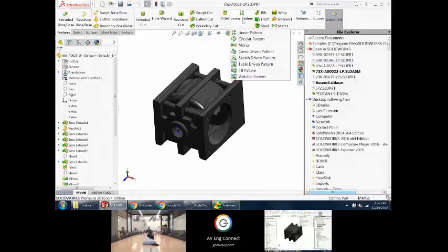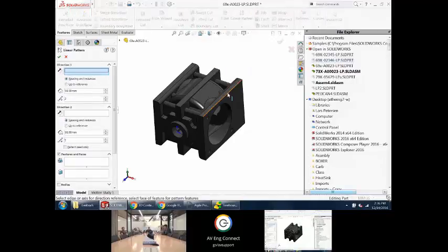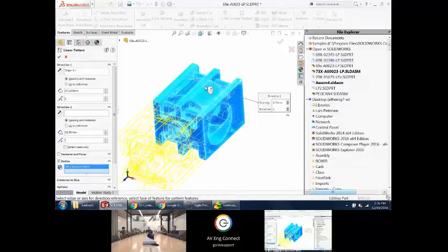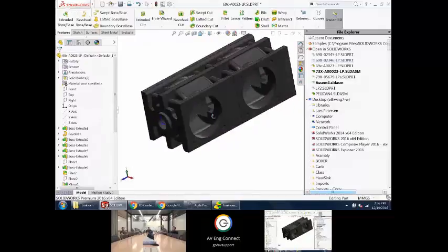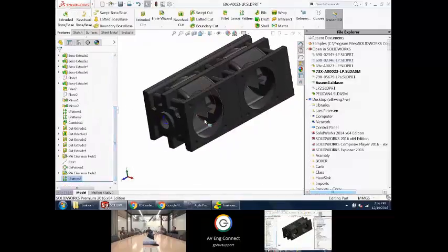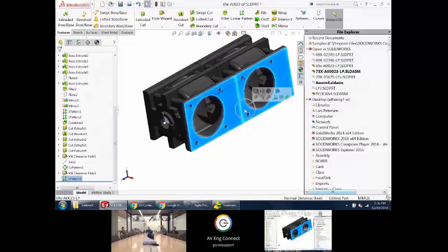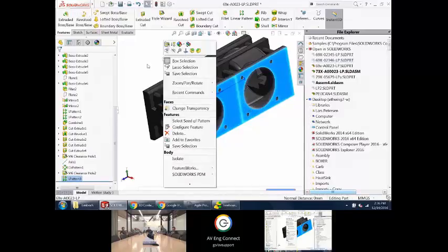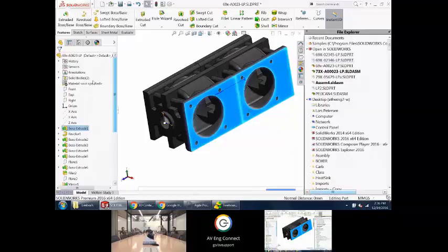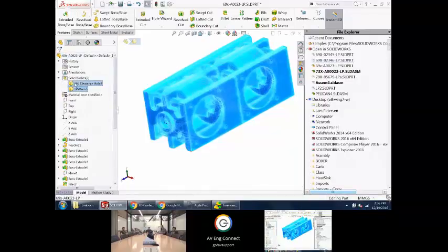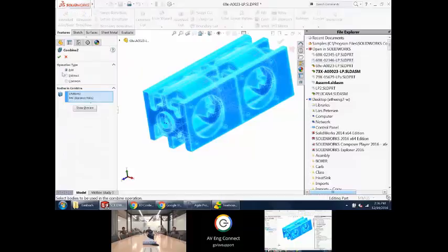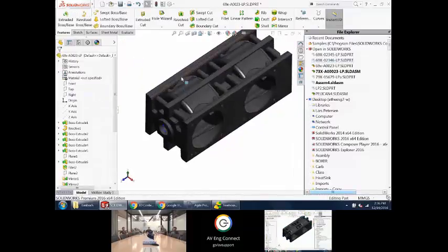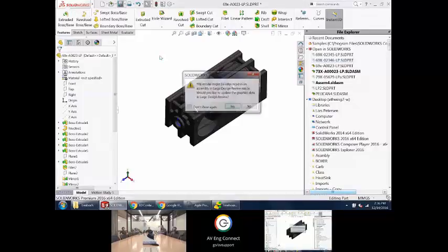What I'm going to do here for this part is I just want to make a 4-cylinder out of this. So I'll do a linear pattern. And instead of copying a feature, I'll copy the whole body. 4 cylinders, just that easy. All I need to do is pick multi-bodies. When you pick them in the feature manager tree, here and here, a right click will give you a choice to combine, and you can do a Boolean addition to get that one working.